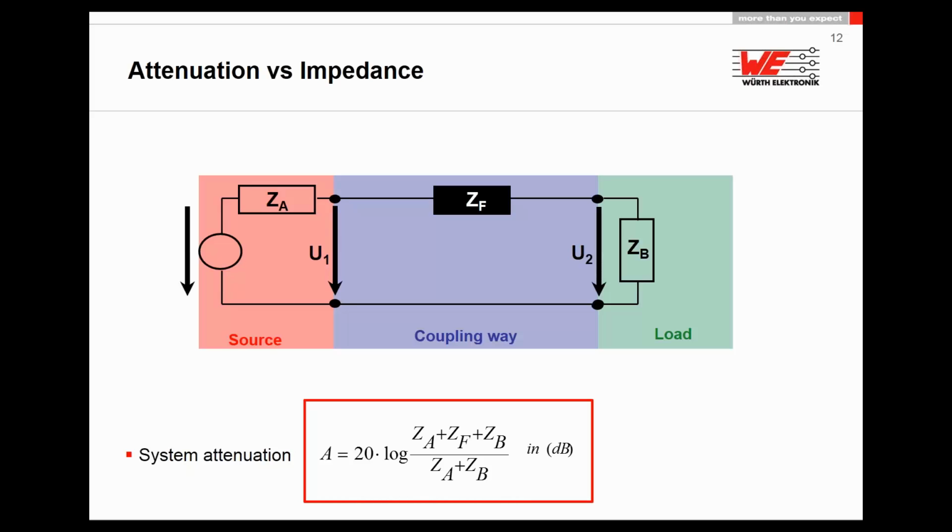But in the real world, you can imagine you are manufacturing something like a small remote control. You put this remote control on the desk and it exceeds the limits by 20 dB, and now please tell me what is the system impedance of this remote control. Oops, not 50 ohm anymore. What now? Well, this is not so easy, but you have to start with some real values.